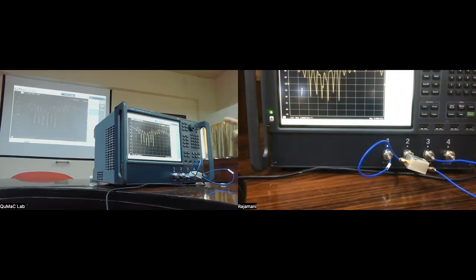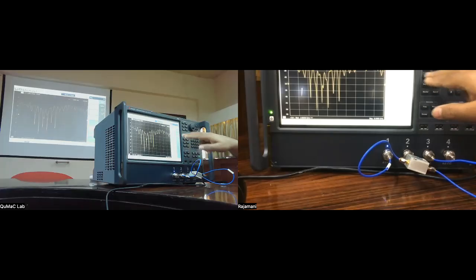And this is again the 2 to 10 gigahertz range, which is the spec operating range of this instrument. Let me just increase the number of points. Sometimes I'm seeing resolution issues here. So I've now increased it from 200 to 1000 points. So that's S11. I will put this to memory.